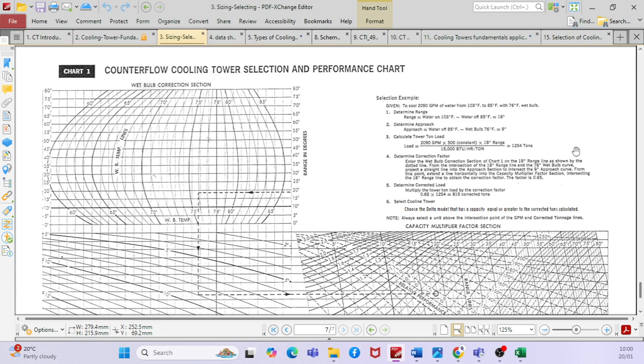After that, we also need to calculate the makeup water. Is this also done by the cooling tower manufacturers, or is it something we have to do separately? We can do it with the help of the cooling tower manufacturer. They will tell you the drift losses, the blowdown losses and the evaporation losses. You can also calculate a value, then verify it with the manufacturer, same as when we prepare the schedule, then verify with the manufacturer and update our schedule based on the manufacturer, right?